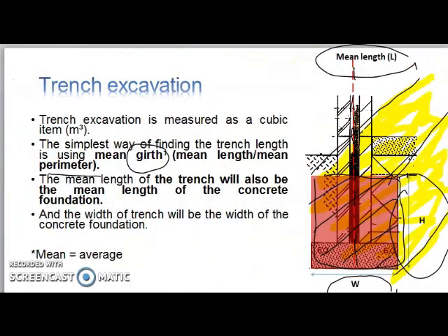So before that, let's try to identify the unit of measurement first. Trench excavation should be measured in meter cube, meaning once you take off, you will need to dispose it as well. So disposal for trenching is also measured in meter cube. Okay. So the simplest way of finding trench length should be using the mean length.